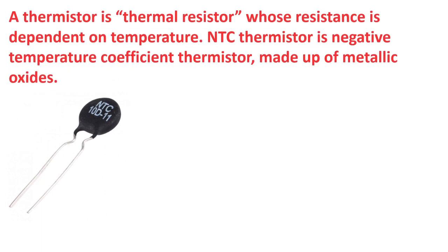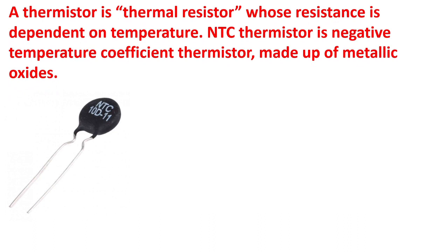The thermistor is a thermal resistor and its resistance is dependent on the temperature. NTC means negative temperature coefficient. In this discussion, we shall use an NTC thermistor with its room temperature resistance 100 ohm.